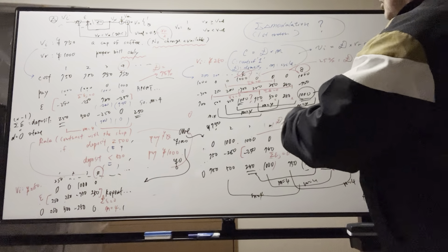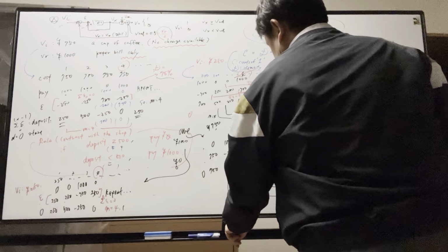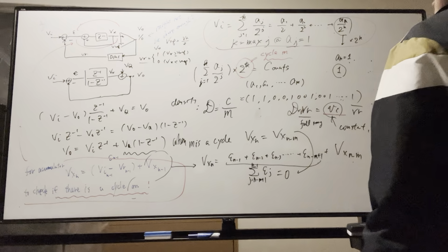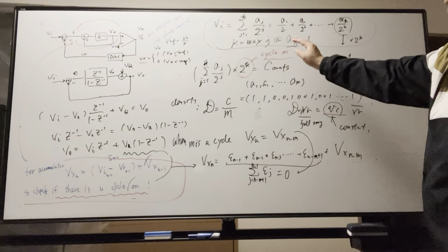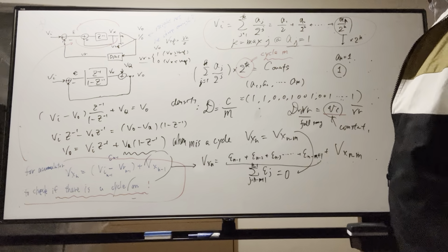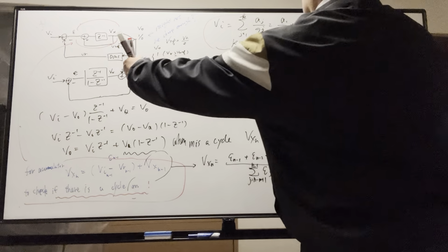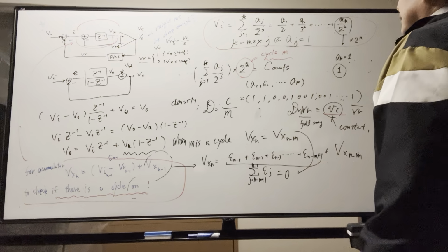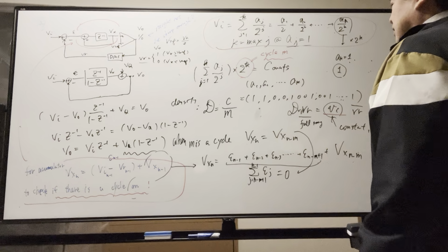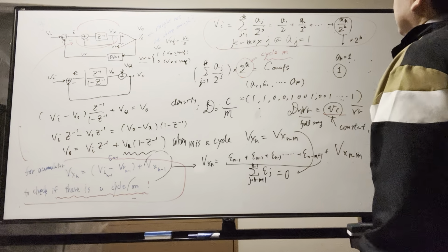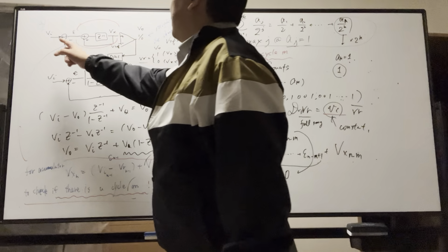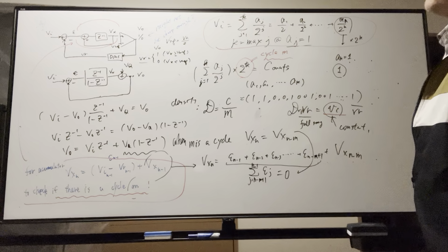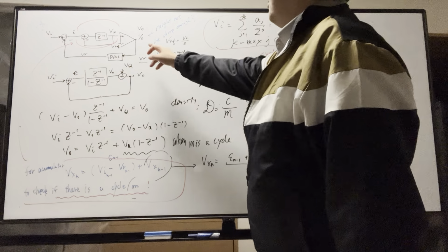It explains the specific case where we need to interpolate between rational numbers. Rational numbers, in the sense of a limited series for a given accuracy, are explained exactly correctly by utilizing this sigma delta modulation after some appropriate filtering.